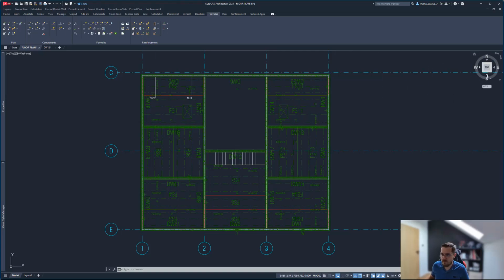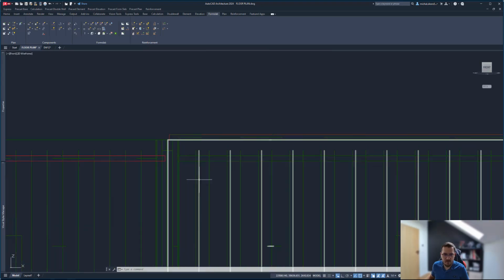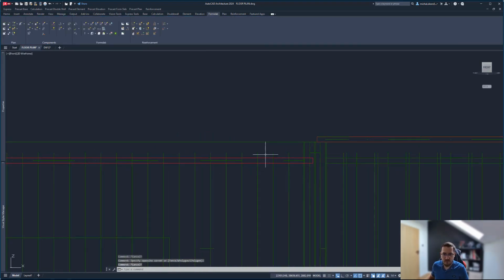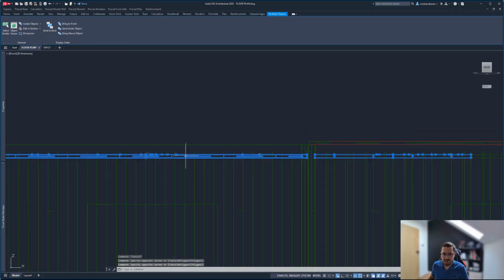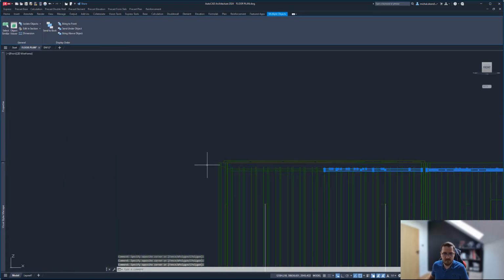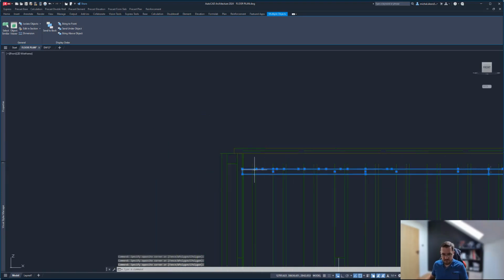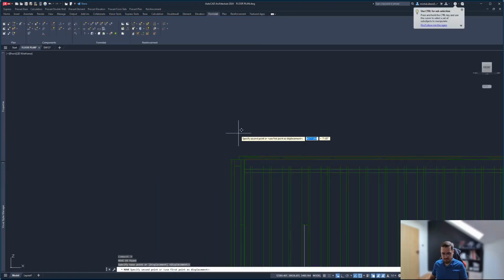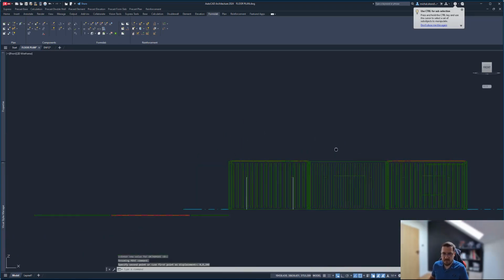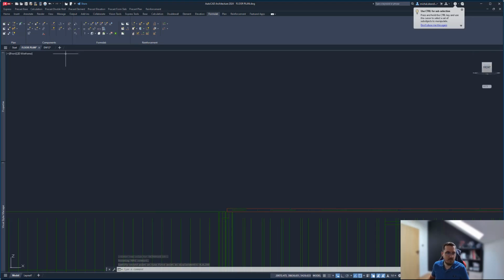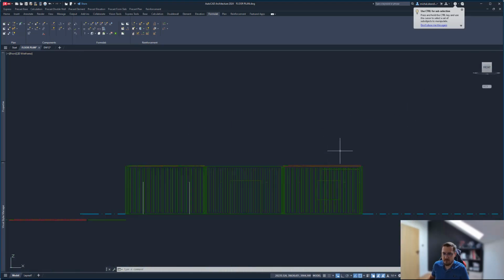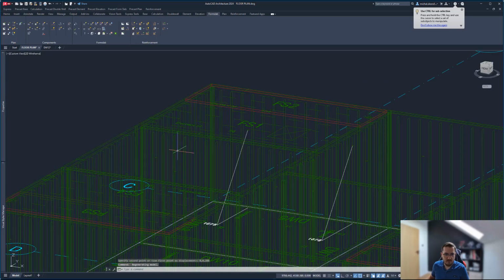And with that, I'll just move to the front view and check the slabs that are too low. Those are the slabs that we want to move, and those as well. What I'll do is move them with displacement. So we're going to use 0 displacement, 0 here, and 200 to the top, and that's perfect. So all our slabs are now at a proper level. Yep, they are good.